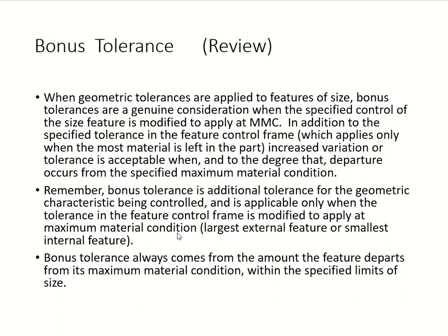And if I have to simplify that for you, if you have more material, the standard tolerance is not going to work anymore, yeah, because you've got more material to your feature, so you have to come up with a bonus tolerance to account for that. So bonus tolerance, again, we're going to count from the maximum material condition towards L, towards least material condition.